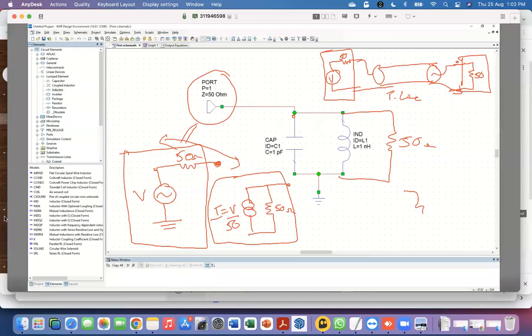One is sort of obvious, that this transmission line should not dissipate any power. This, of course, is impossible at room temperature operations because these are all made out of metals, but it can be made small enough. But more importantly, it should transmit this power, which is now going to propagate as a wave along this transmission line, without any reflections. And that requires this transmission line to have a property Z0 also equal to 50 ohms. And this Z0 is what is called characteristic impedance.